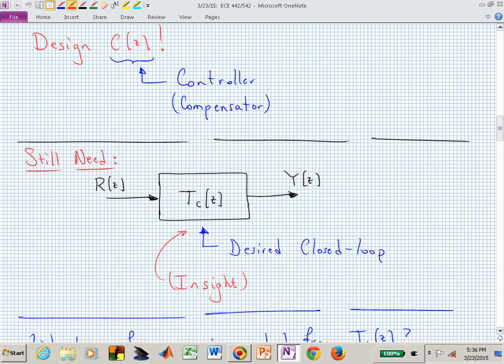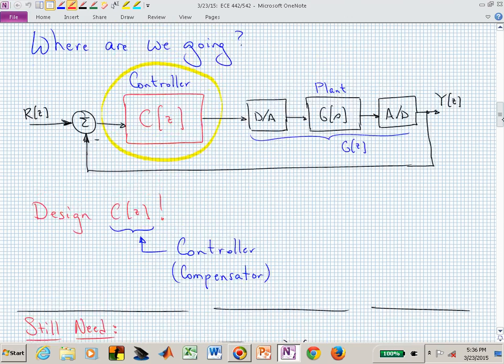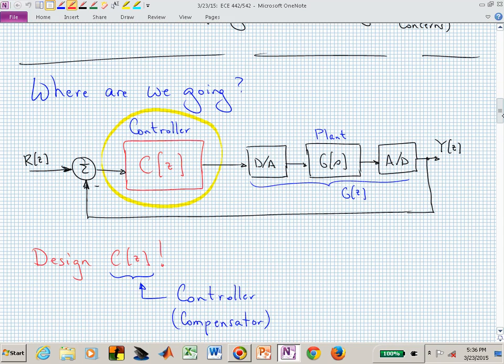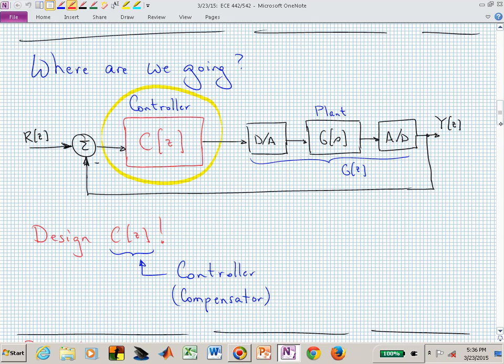Meaning, if we're interested in that closed loop behavior, and if we lump it all into this capital T sub C of Z, a closed loop transfer function, which isn't just the product of C and G, is it? It's CG over 1 plus CG.